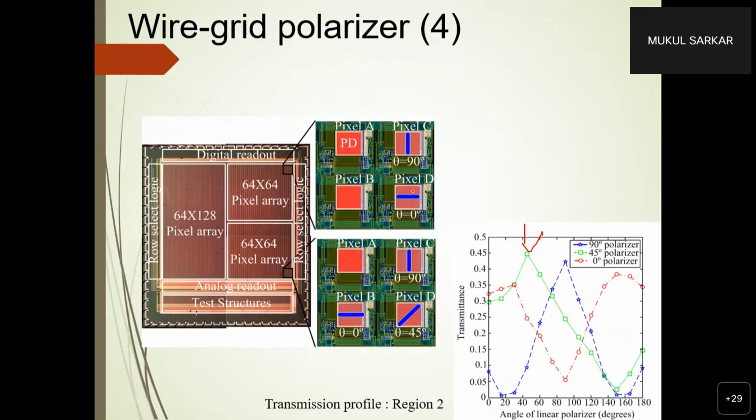If by using circuit architectures like chopping and other architectures, you're able to lower the pixel noise substantially, then you do not need to burn more current, and therefore you save in terms of power.